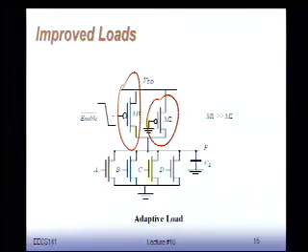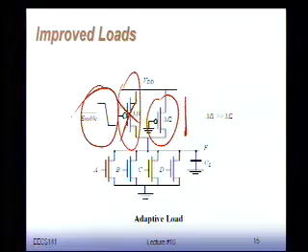Then when we're done, we turn off this device, and we have this for the static operation, when we're not doing anything, a very large resistance, which means small power dissipation and larger noise margins, because my resistive divider gets a lot better. So by combining the two and having a control signal flipping one of the two on, I get a better device.